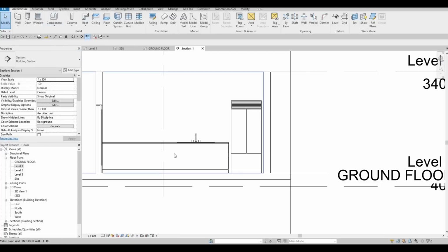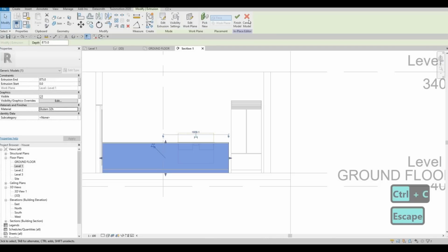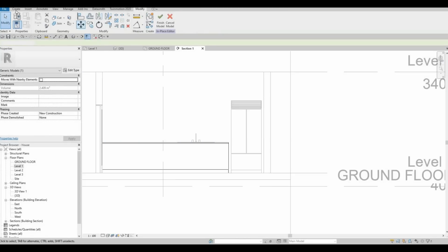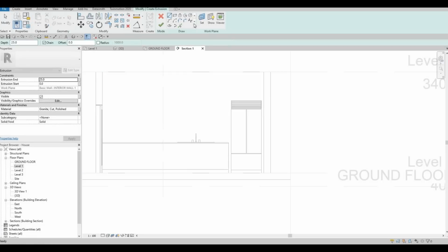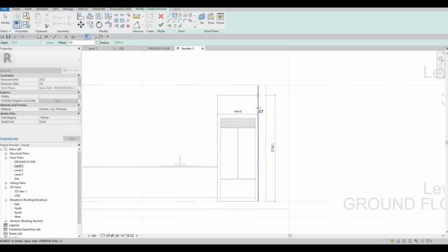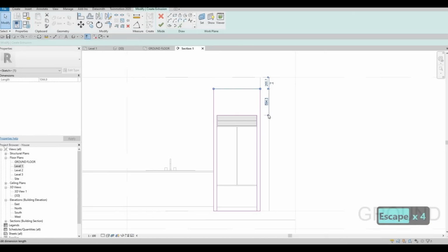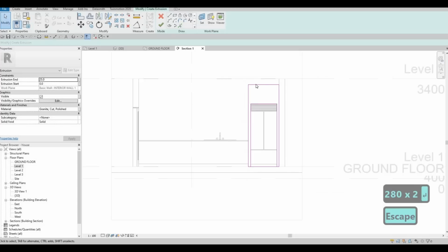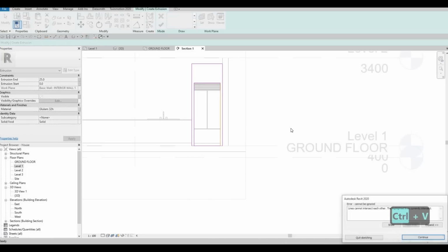So here, go, and then we could add the same one because we added column 32. So now here, delete that, and then edit this, actually create this one, and then pick a plane, and then let's select this back right here, so the back wall, and then add a rectangle around. We want to make sure that the height is around 2800, knowing that our total height is 3000. That is basically 200 minus for the height, so that when we add the 200 thickness floor, it will be placed right here. It's not going to overlap. So now we click on right here, glulam 32, click on finish.